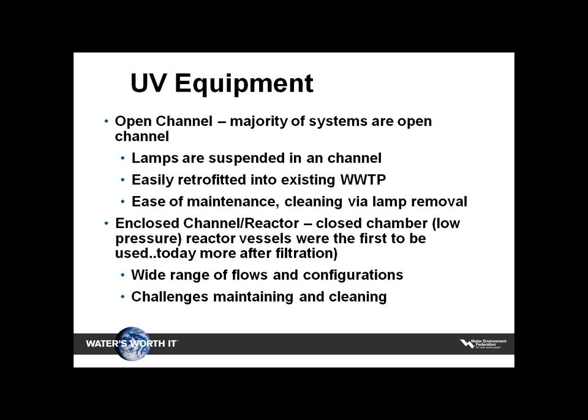So generally we see two configurations. We see open channel, which is probably a very large percentage of what is used in terms of basic level disinfection. Lamps are suspended in the channel. They're easy to retrofit, easy to maintain and access. And enclosed reactors.